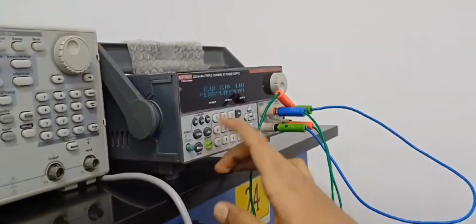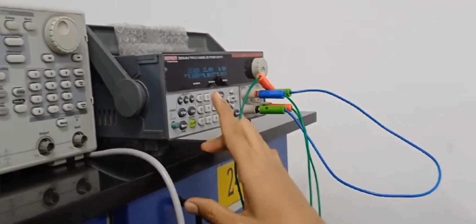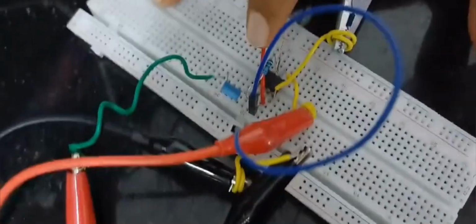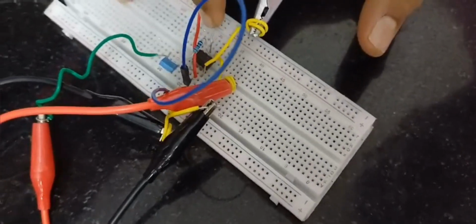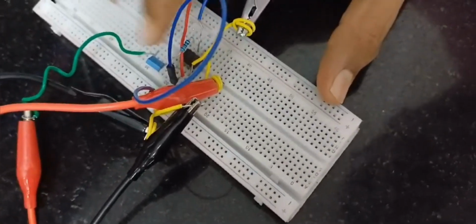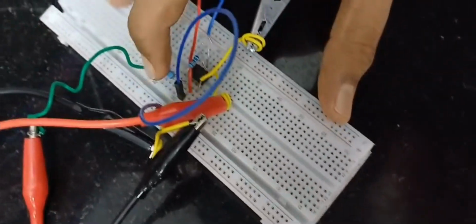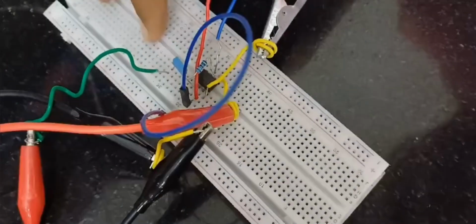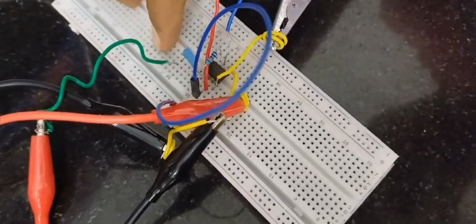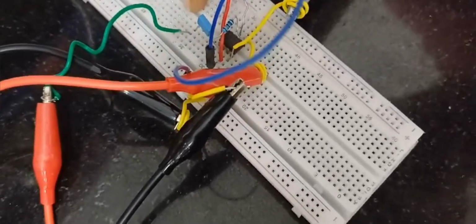So we are giving 12 volts of voltage input through channel 1 and channel 2, and we are going to check the output across pin number 2 and pin number 6. The output is measured across pin number 6 and we have connected a resistor across it. Then in series to it we have connected a capacitor, and we are giving an input of sine wave in series to the capacitor.